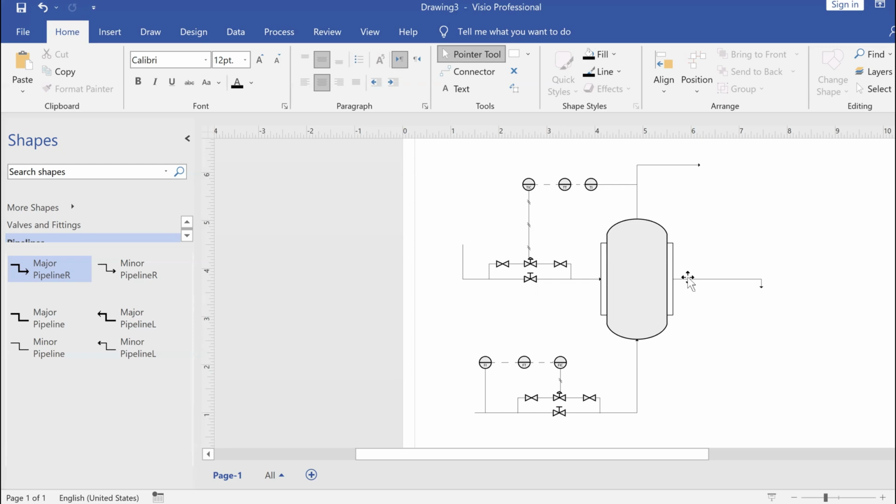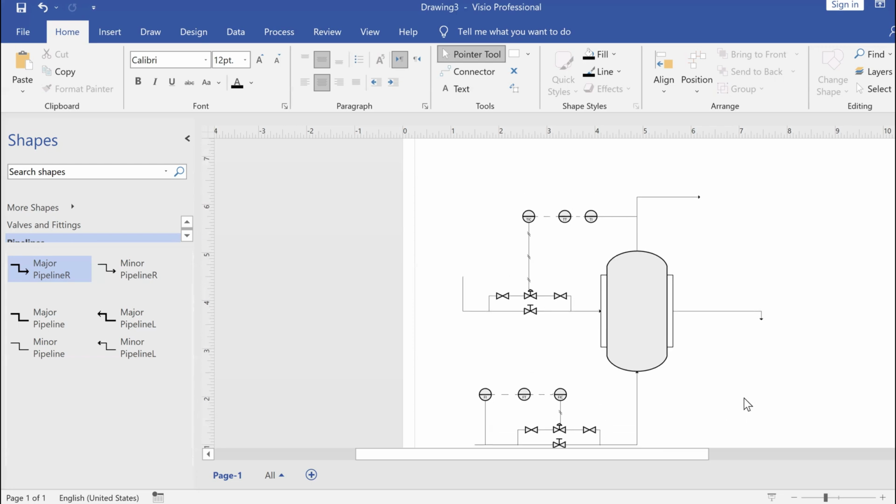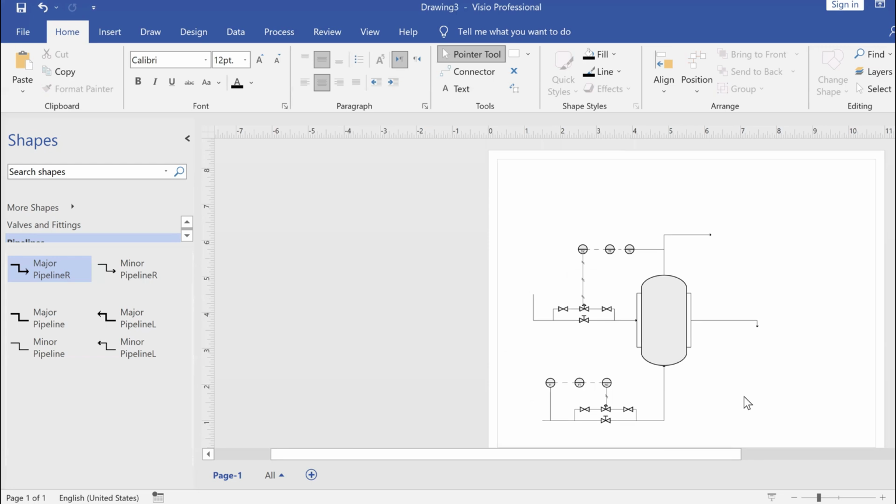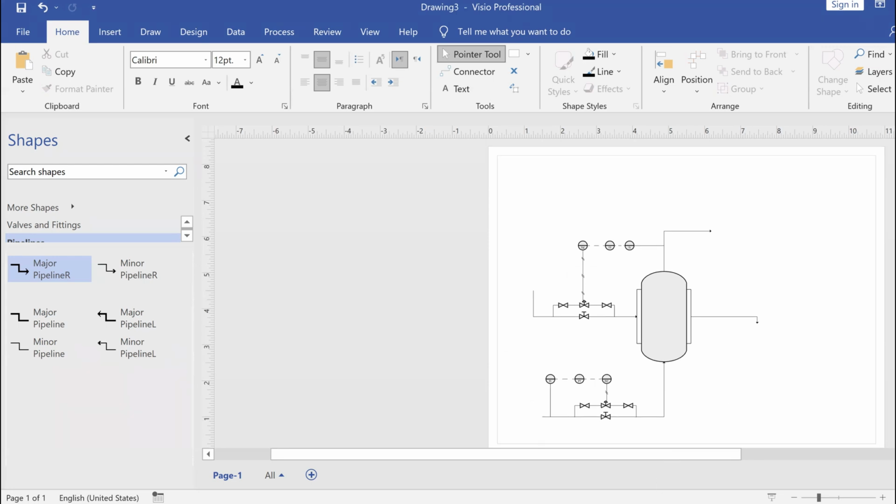What we do is we add this control loop, the flow control loop. The flow rate will indicate the amount of flows going on in the reactor. It will send the signal to the transmitter and a signal to the indicator controller. This will order the valve, whether if it's too high, it will just decrease the flow rate, and if it's too low, it will increase the flow rate, and so on. It's a very basic, straightforward loop, but it's a very essential flow loop. And this way we finish the P&ID diagram for the reactor with a cooling jacket.